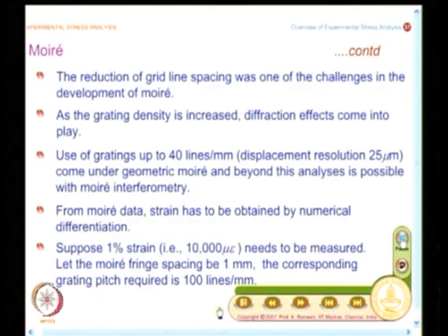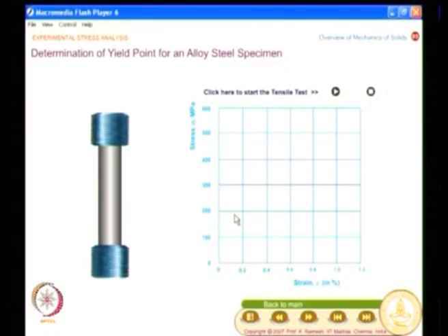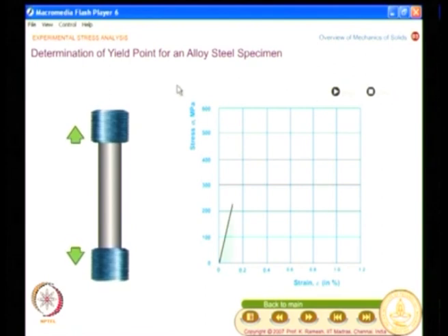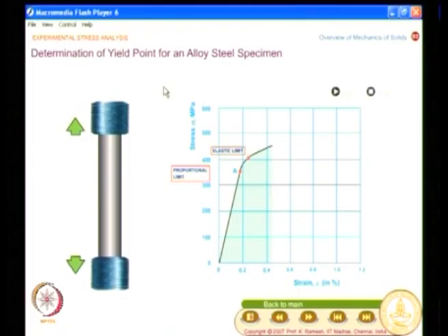And what I want to caution here is, I said that long time back, the example of somebody going to a doctor and then finding out whether 105 degree temperature is small or big. He should not refer to an encyclopedia. And when you have difficulties in finding out the yield point, which is not marked sharply, then you have the offset method, and then you locate the yield point on the stress strain curve.